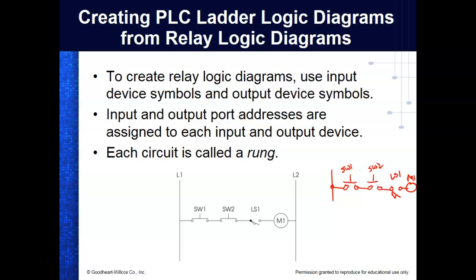These rules that I've given you are the revised rules that more precisely match what we learned in motor controls. So everybody okay here? These lines are drawn normally closed, by the way. This would be the actual normally closed momentary contact push button. We took two connection dots and then drew the actual connection on the bottom.